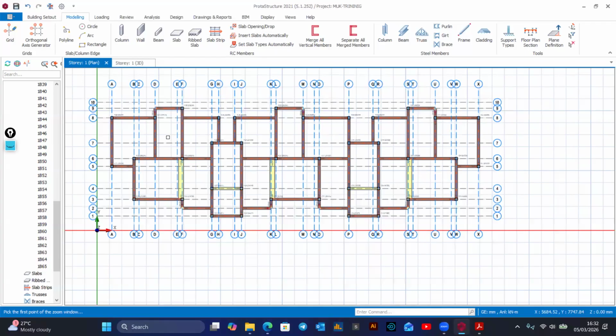But then if there is parking to be used, maybe this level there is parking, but below it the place can still be accessed. It's now a basement already. You get it? So if it is not suspended, if you have a slab on grade, you don't model slabs there.